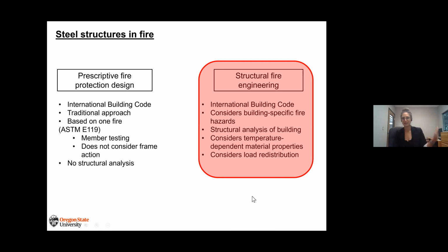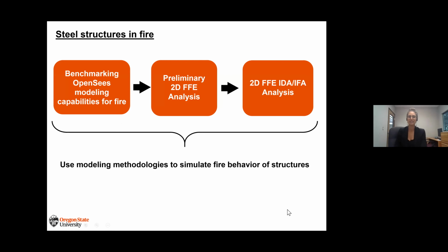We're throwing hourly ratings out the window, and we're using all of structural mechanics and our knowledge of structural engineering to allow buildings to maintain load-bearing capacity throughout a complete design fire. So what we've been doing so far in OpenSees is using, again, the latest version of OpenSees and temperature-dependent material properties. We first developed benchmarking examples in OpenSees to highlight the modeling capabilities of OpenSees in fire,